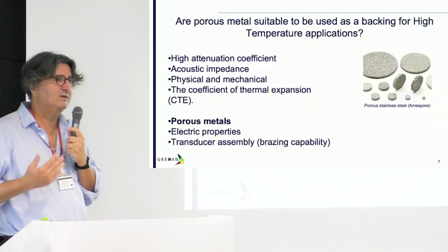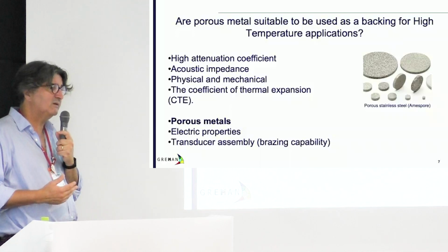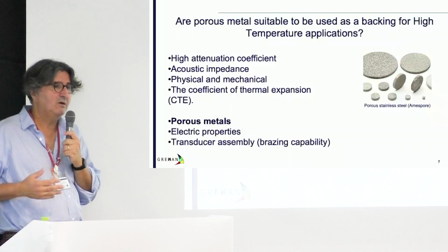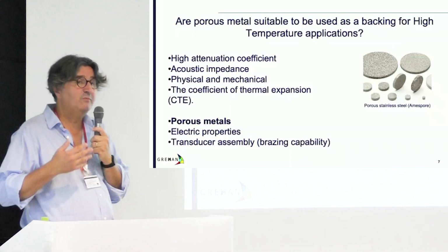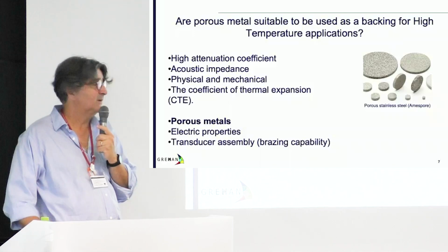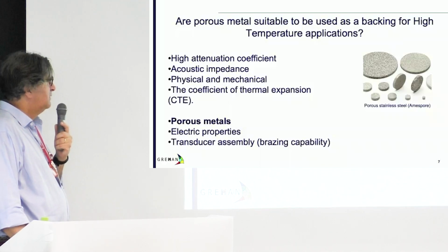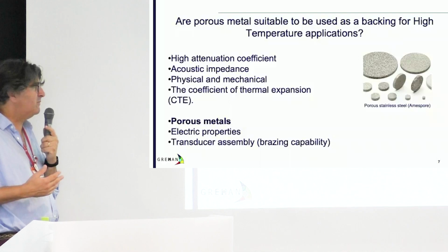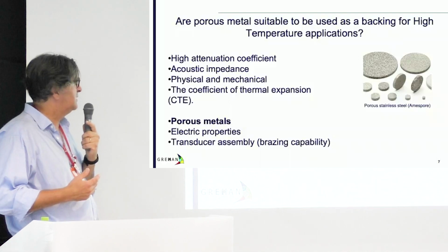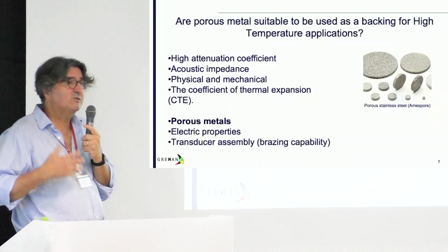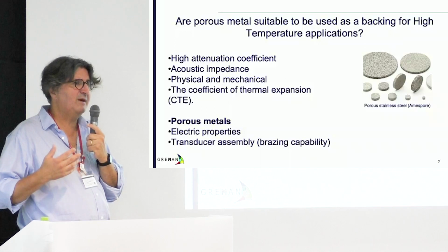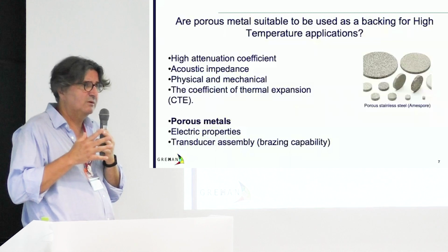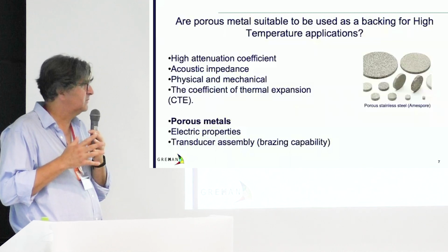In particular, these porous metals are used for catalytic applications, so they are known to be used up to 800 degrees. They also have to have a thermal expansion coefficient compatible with lithium niobate, the active piezo material used for transduction.